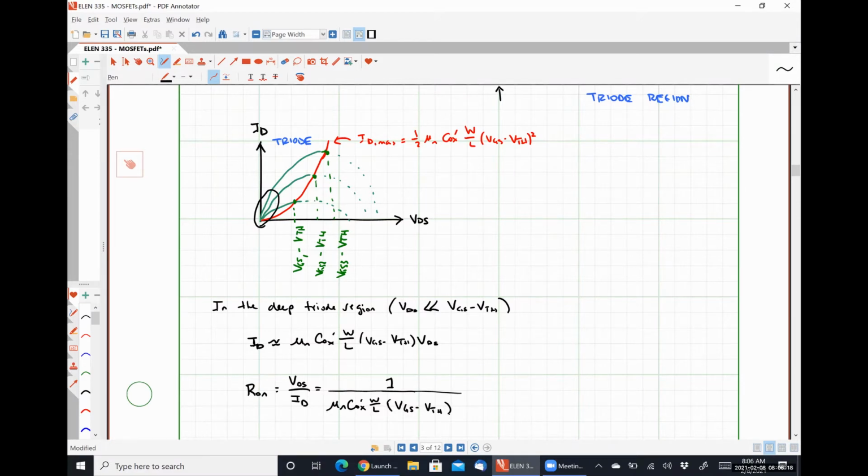The reason why I say that specifically, for those of you who don't get so turned off on this subject matter by the time you get out of 336 and choose to take 438 as one of your senior options next year, the integrated circuits class, we'll go through what it would look like to develop N-well and P-well resistors, high-res poly resistors, and things like that. And we'll see that while we can make good, stable resistors using those tricks, they are typically extraordinarily large in comparison to a single transistor-based device. So there are trade-offs to be seen there.